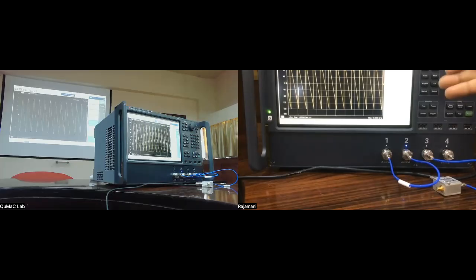This is something just because of the length of the transmission line. And we were seeing something exactly the same when we connected the splitter, because that length is still in the picture. So this is very fast, and the longer the cable, the sharper the slope of this phase change would be, because delta t will be larger. So on that screen, you will get many more things packed into the same length.